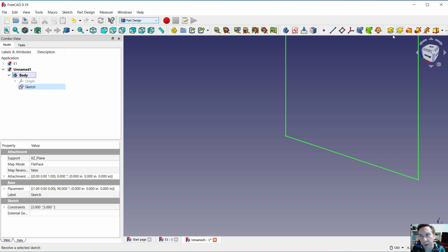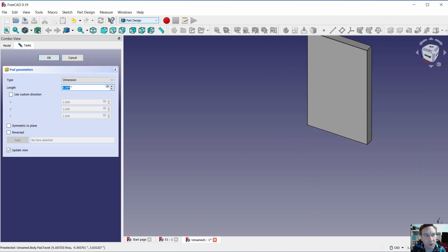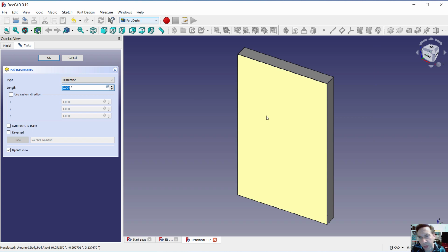And what we're looking for is this. Now those of you who are familiar with other CAD systems, Extrude is known as pad here. So go ahead and select pad. All right. Now you could do zoom to fit again if you like. There's a fast key for that. I think it's V and F or something like that.